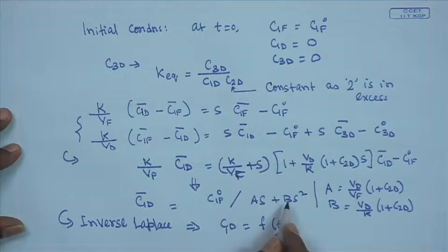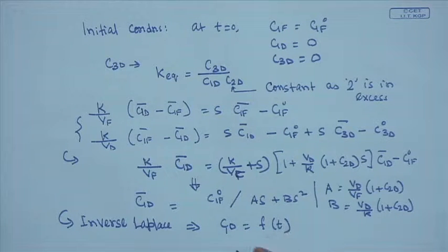and can obtain C1d as a function of time. This is straightforward. We can really do that and get the profile of concentration of aniline in the dialysate side and how it varies as a function of time. So, this is the modeling of a batch cell, where the dialysis separation is enhanced by an external chemical reagent. This must also be known to a student, how we can maximize the driving force during a dialysis process and how to model the situation.